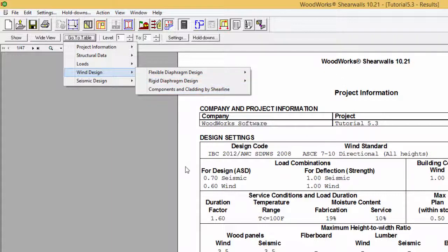The flexible and rigid diaphragm analyses are both available in the results for wind and seismic. The loads are not distributed in the same way for both methods, thus it is important to consider both cases, as it is hard to predict for some structures whether it will act as a flexible structure or a rigid structure.